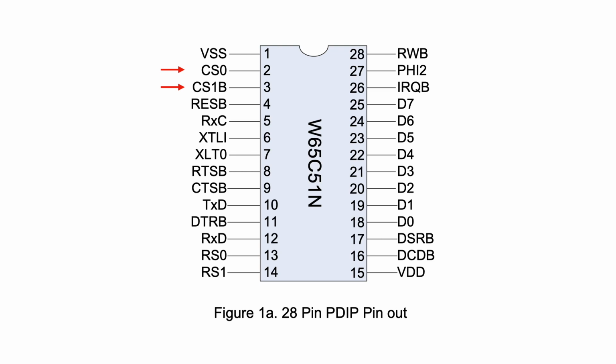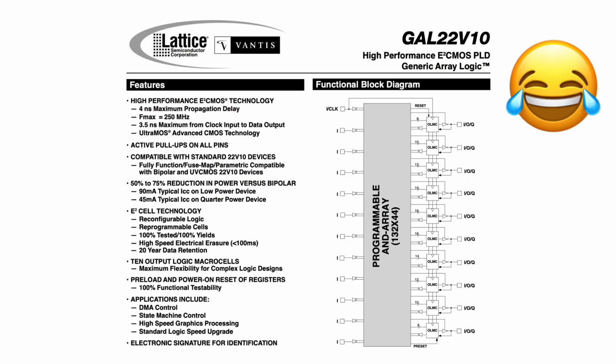That's 3 chips, and this guy's going to use another GAL, isn't he? And the answer is yes, I am. And I think it's perfectly justified because I actually want to be replacing 4 ICs with this solution here. Recall that the address and data buses are going to be buffered to overcome the low fan out of the 6809. Well, I want to give the same treatment to the RW output on the CPU, and all the current bus transceiver inputs are already accounted for.